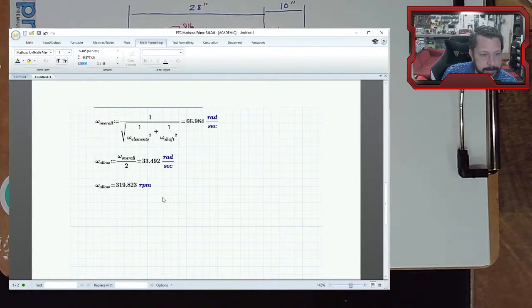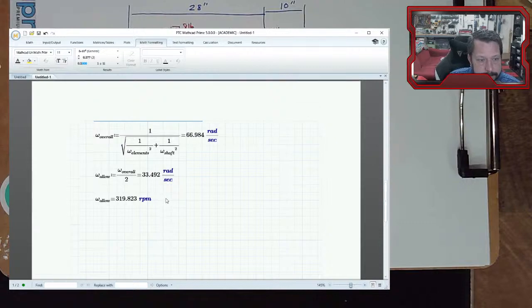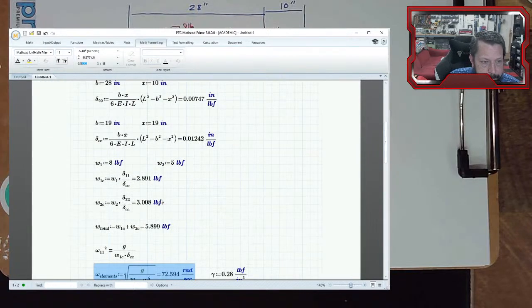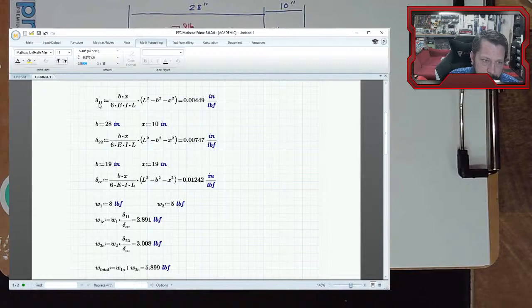All right. So at that point I was saying that it is a little more involved to calculate the critical speed of a shaft. It's not terribly complicated. There's a lot of little pieces you can get lost in, as far as understanding what the influence coefficients are doing. So the 1,1s and the 2,2s and the CCs, what do those subscripts mean?